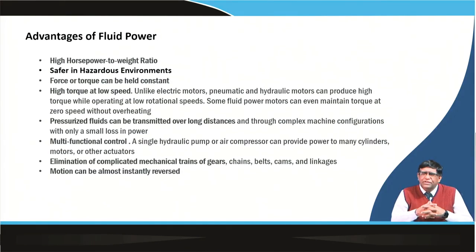Then it is safer in a hazardous environment. As I already told, in an underground coal mine where there is fire damp, if there is any spark because of gear friction, or heat, that gas may get burned. Or when you make an electric switching, the momentary spark that comes can ignite an explosive gas. So in such places, if the power is transmitted by a non-inflammable fluid or by air, there will not be any such accidents.